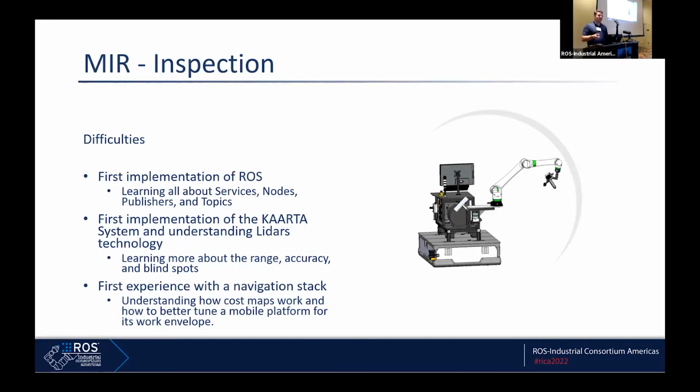Actually, CARTA was the system that we used. CARTA is an out-of-the-box solution that you can go buy. It has a Velodyne LiDAR, a 2D image camera, and an IMU all in one box. It's on top of the Linux platform itself. You can go in, map a room, and it will register the room and its own odom data by itself. Then it'll stream that back into ROS because there are actually ROS drivers for it.